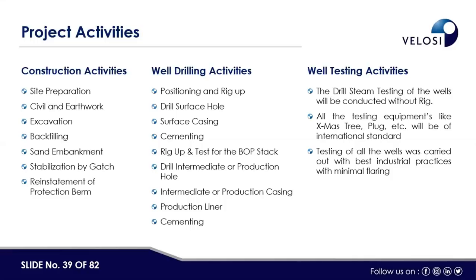Then while drilling activities: positioning and rig up, drill surface hole, surface casing, cementing, rig up and test for BOP stack, drill intermediate or production hole, intermediate or production casing, production liner, and cementing.